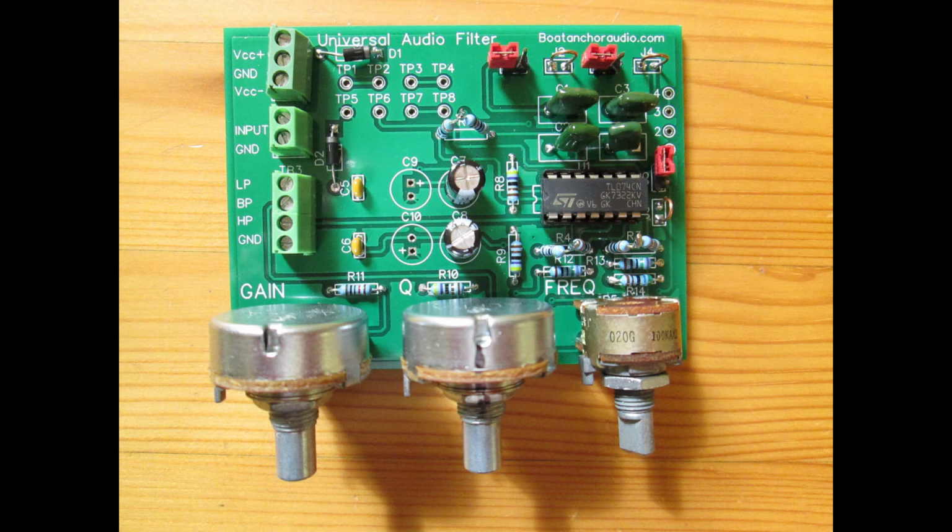The other reason I use something like this is it has a THD that will meet my specs. Now, I could spend a lot more money and buy a high-tech chip that might have a THD of 0.0005. That's wonderful, but how do I test it? I can test down to about 0.001.